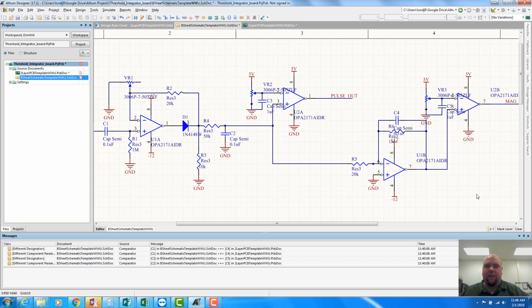I know I'm switching into professor mode here instead of YouTube video maker mode. But normally that doesn't make any sense, right? We have two op amps in the package, might as well use those two for this stage and this stage. One thing to note, and it's one of the things that I don't like about the way we present packages here, is that this pin 8 on this op amp, and this pin 8 on this op amp, are actually the same pin. So they're the same pin on the same physical package, which means we should have the exact same signal connected to these. The problem is, this op amp here, I wanted to connect 5 volts and ground.